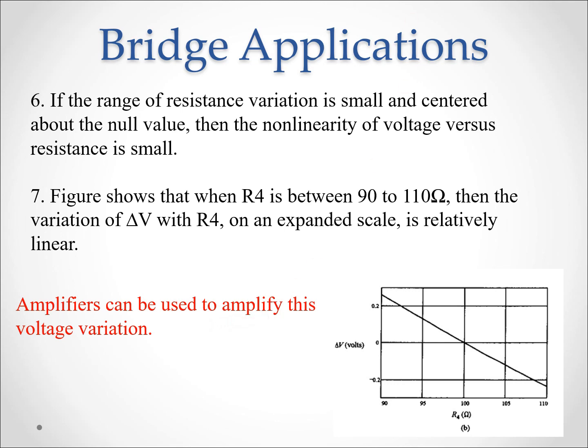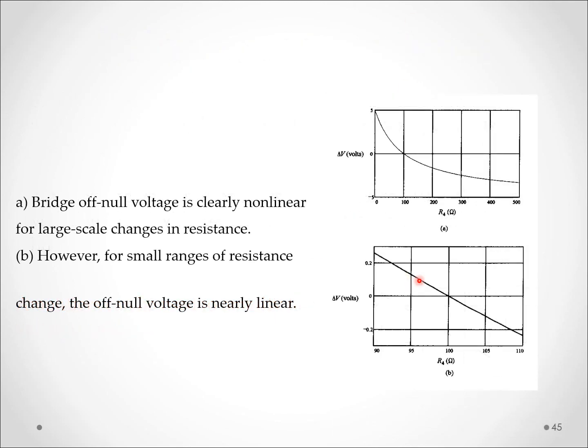Bridge circuits are fantastic tools for converting resistance variations into voltage signals. However, understanding the potential for nonlinearity is crucial. By keeping the resistance changes small and centered, we can ensure that the voltage output accurately reflects the variations we're interested in measuring.